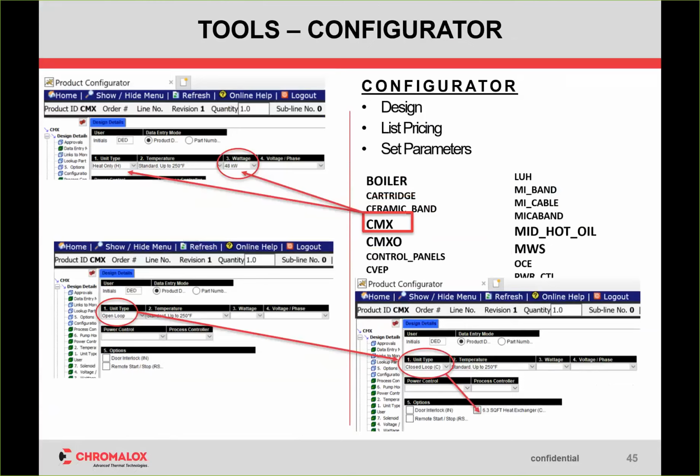The CMX, as I started this whole presentation with, we talked open closed loops cooling, but something I mentioned last week and actually held true because it came up twice after our presentation, that our CMX, the water glycol system, the lower temperature one, is only rated to 24 kW. But you can take the exchanger out of it, the cooling exchanger, and put a secondary heater in it, essentially doubling the kW. So we have kW offering. There's not a gap between 24 and 50, which is the low end MOS. It's a special make CMX. We have a 36 and a 48 kW. I want to make sure everyone knows that on the call, because there isn't a gap there. I guess not as well known that is an option available.